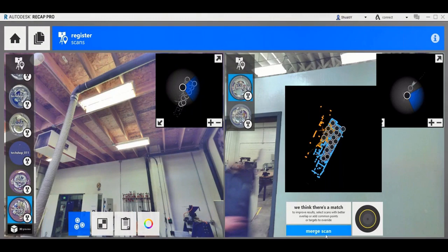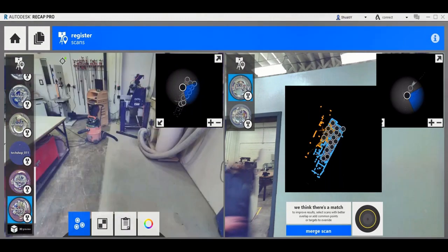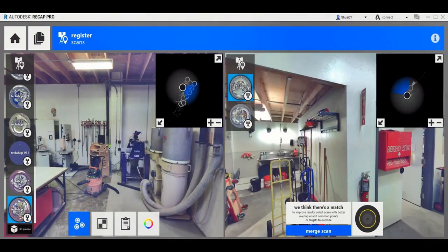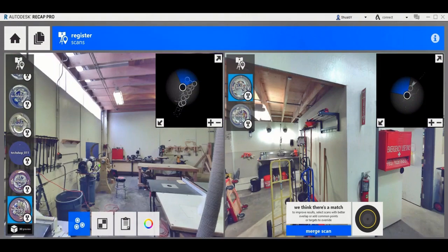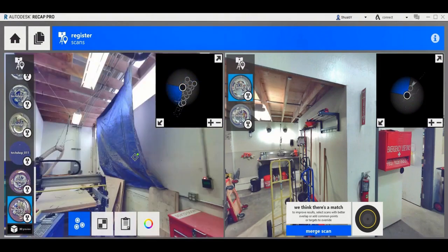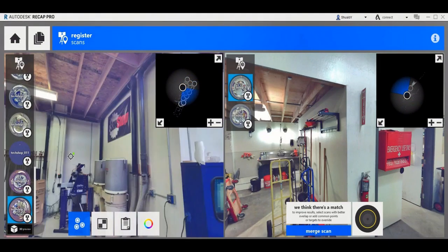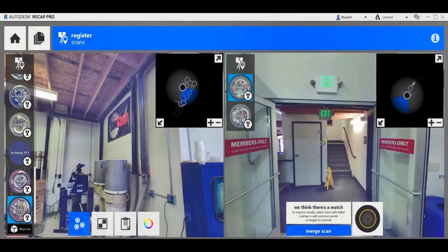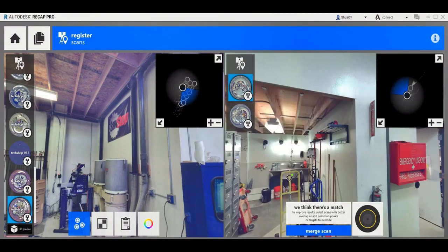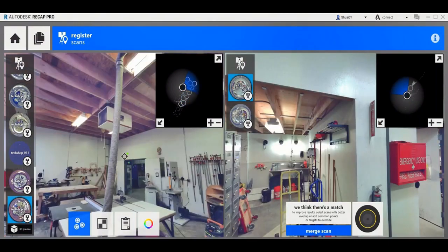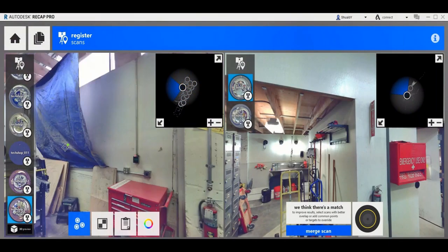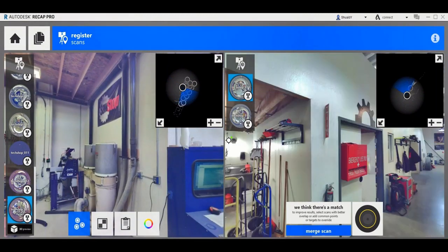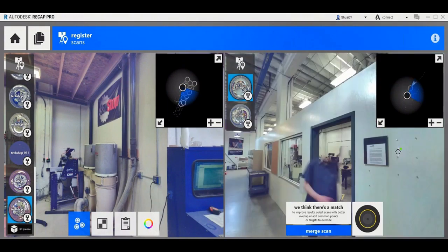That means that it's not the greatest of matches, but we can actually stitch it together. So it's always good practice to check the surrounding environment first, to see if it matches what you're seeing there. Again, it's nice to do a scan when it's vacant, otherwise you would get floating people around that look like poltergeists or ghosts. So it's good practice to have a vacant area when you're scanning.